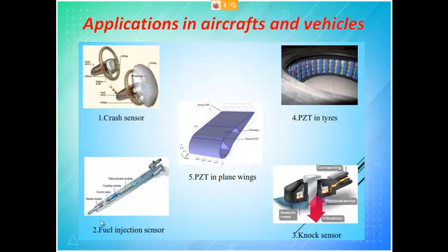Whereas in a diesel engine, what we do is, inside the cylinder we will supply only air, and we will not supply diesel initially. Then we will start compressing. There it is 1/16 of its initial volume, okay. That is why we say diesel engines have more vibrations, and the temperature of the engine will be very high as compared to petrol. But the power developed by a diesel engine is more. That is why heavy vehicles are diesel vehicles. You don't go for petrol.